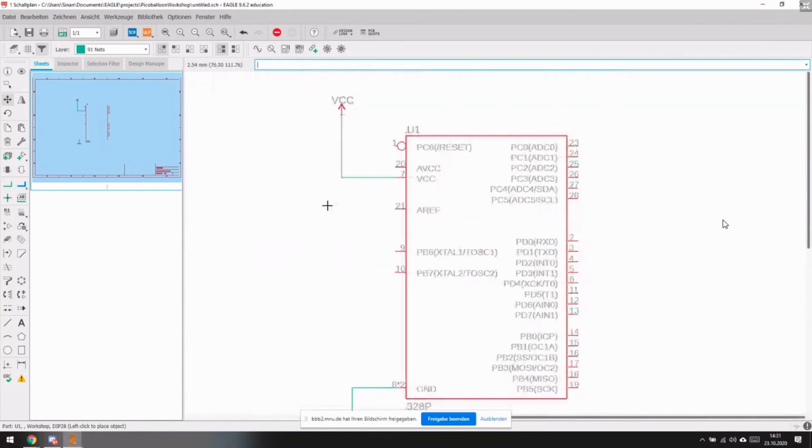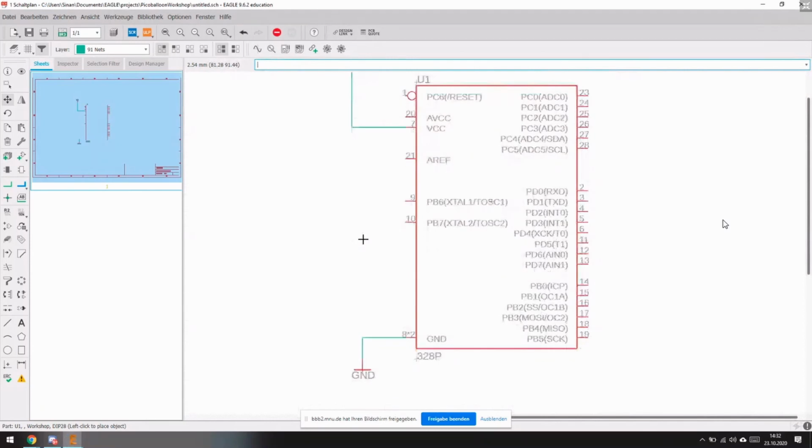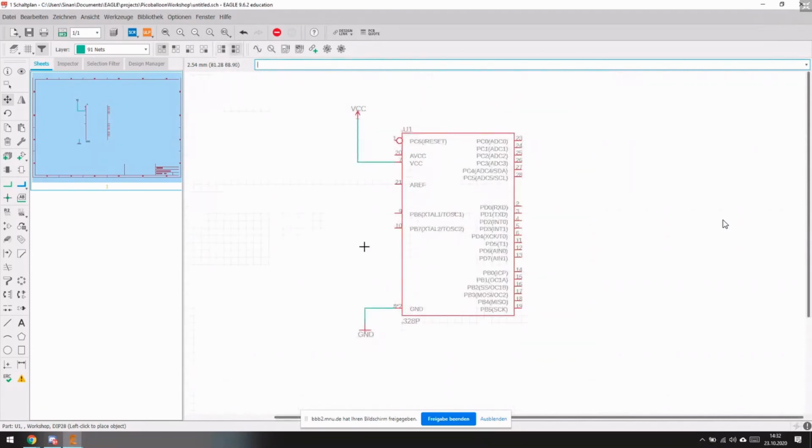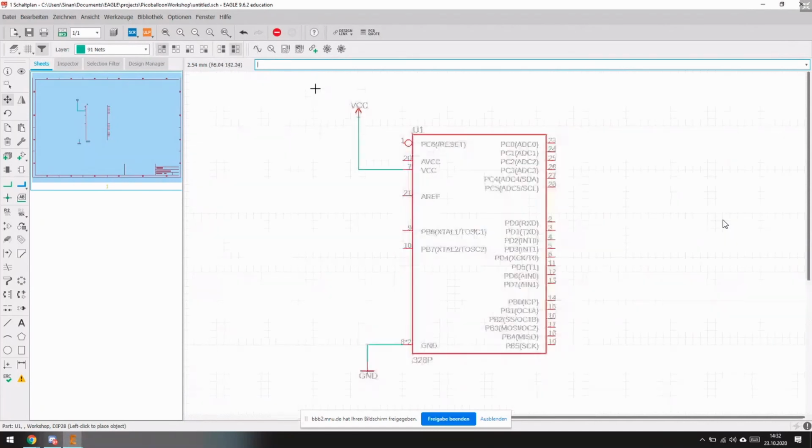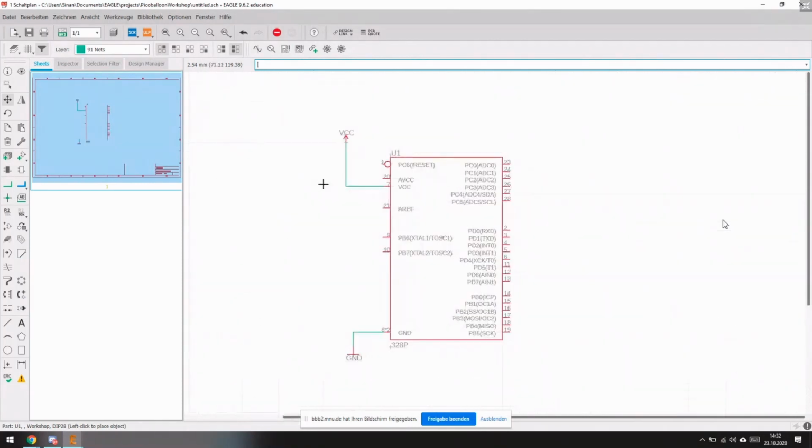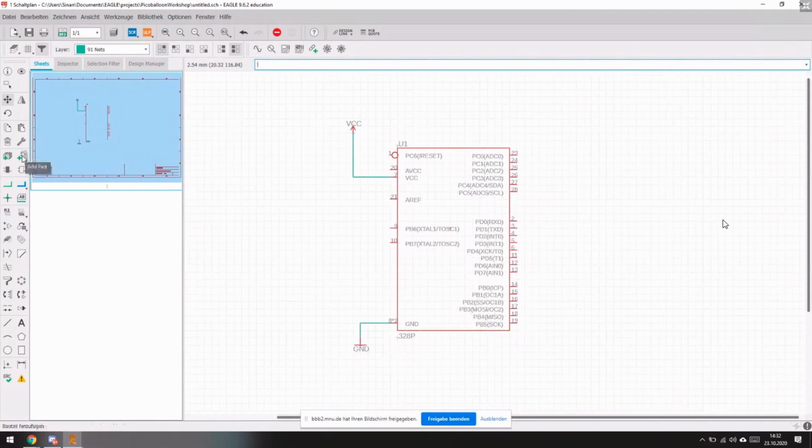So power supplies are not that clean as you might think. If you, for example, take a DC to DC converter, hook it up to a battery, and use the raw output like we are doing here, it could potentially damage the IC with voltage spikes, or it could just run it unstable. So to fix that, we add some capacitors.